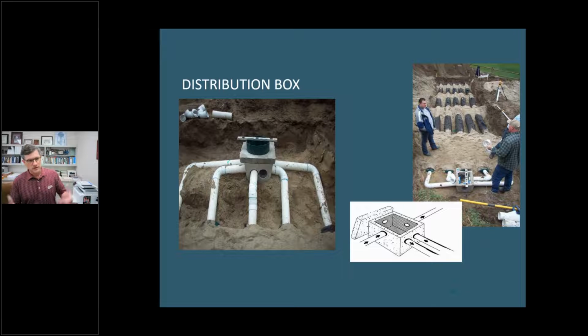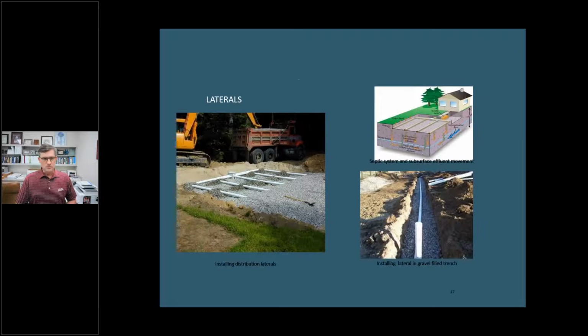So any type of rainfall and anything leaching is allowing that drain field to actually do what it's designed to do, and that's to leach into the soil. That's what we'd like to see. All right, so this is another where we're looking at a gravel pack where we're putting some gravel in, and again, trying to create the environment where you can have good effluent absorption.